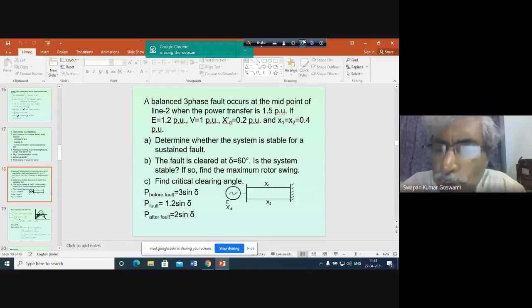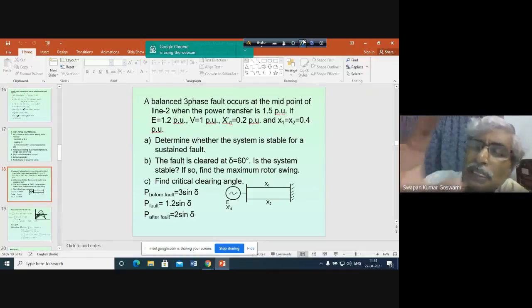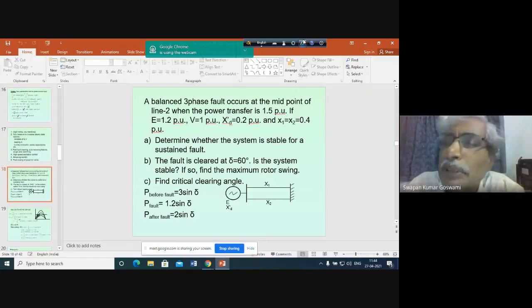The transient period is short, but the transient stability study, to determine whether the system will be able to maintain synchronism or not, will require some time. It will swing for some time. During that time when the generator is swinging, the reactance of the generator may be represented using the transient reactance. That's why we shall be representing the generator using the generated voltage and transient reactance.